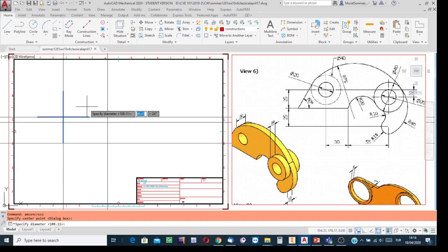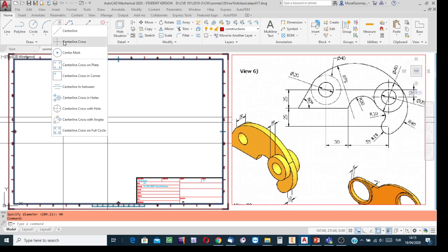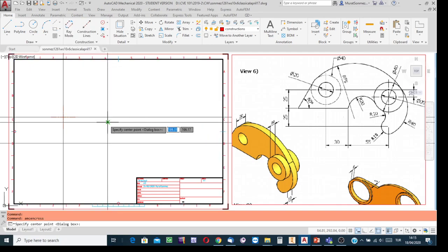If there are concentric circles, write the size of the outermost circle. Here the diameter of the outer circle in this group is 40. You see this number is over there, 40, with the diameter symbol. Write 40, press enter. I am sure I now have the axes of symmetry in the correct size. Start the process by clicking on the button, and then I know that this point is the center of the second group, indicated as the center.